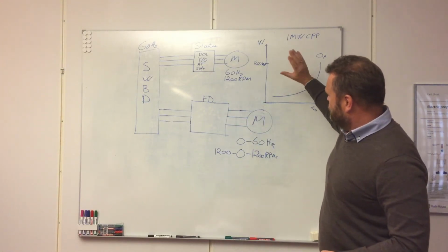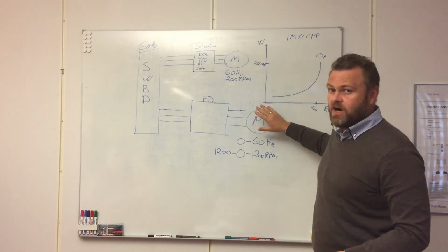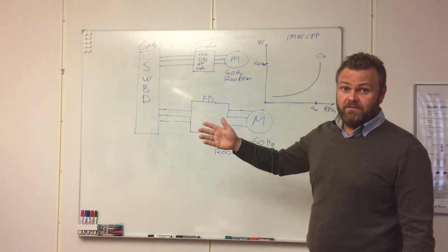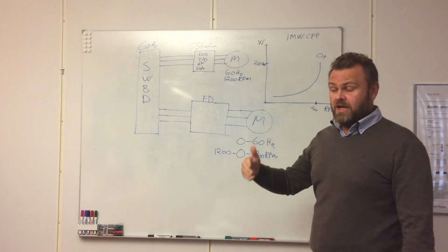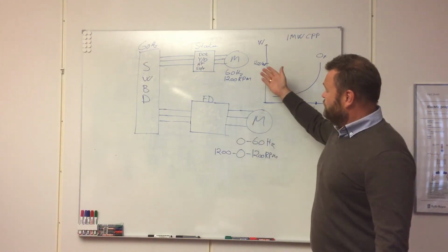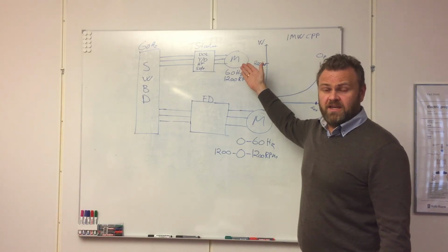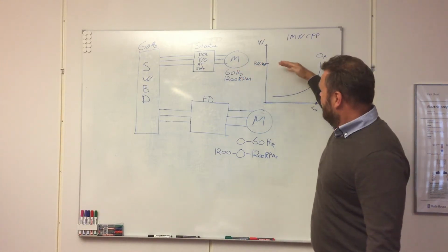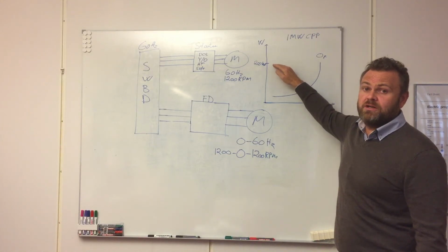So that is just a short introduction to the starter equipment and the frequency drive. Why do we choose a starter in some applications, and why do we choose a frequency drive in some applications? Because if you have a cargo vessel, let's say, that is approaching harbor once a week, using the tunnel thruster just a few hours a week, well, then what he can save isn't really that much.